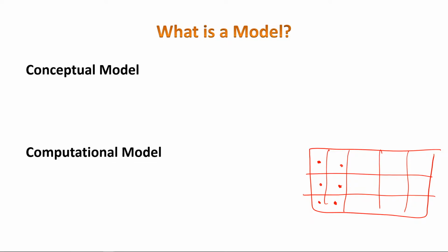A numerical model requires input data from your conceptual model. This input data would be the boundary conditions, the hydraulic conductivity, recharge rate, pumping rate. It will take this information from your conceptual model and simulate the behavior of your system. So why do we need a conceptual model? Because conceptual models provide an understanding of the system and help us to identify data gaps and uncertainty, as I will show you in a minute.